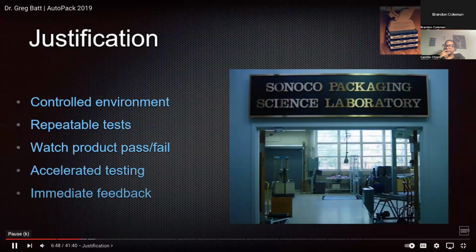Accelerated testing. This is particularly applicable to vibration. We'll talk a little bit more in depth about this, but the ability to take a 10-hour truck ride and simulate the damage potential of that in 3 hours. Well, now I can do 2 of those tests in a day. And that's where you see in your reading where it talked about having, you see your plots and they take out this portion where there's no activity and you're only using the events that were shock events in the lab. That's what he's talking about. And I can maybe shorten my development process.